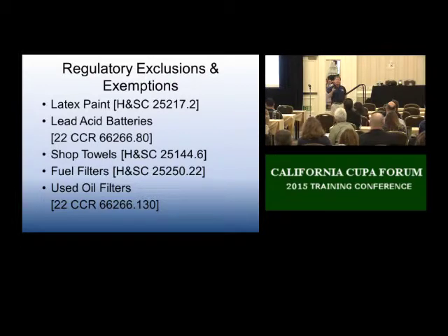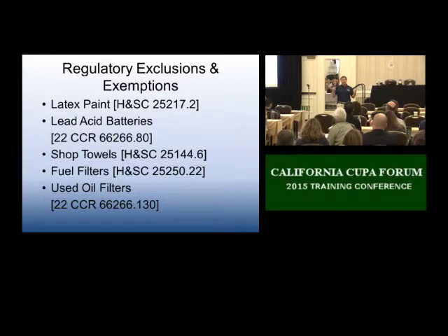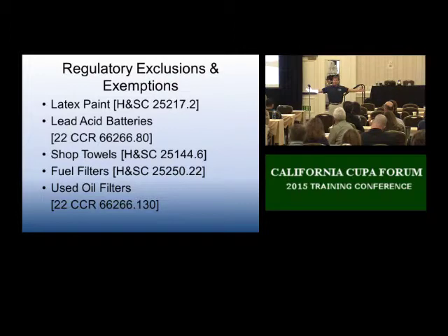But that one test is what captures a lot of waste in California that are not presumptive, that are not listed, that are not identified. If the waste that I produce at my facility kills the fish in 96 hours, then by default, when I go to dispose of, discard that waste, that is a California regulated, non-RCRA hazardous waste in the state of California. And that's truly the biggest fundamental difference that exists in California, and there is no equivalent federally. Going back to the federal criteria, it's one of 40 chemicals. And if it's not one of those 40, it's not toxic federally under RCRA.